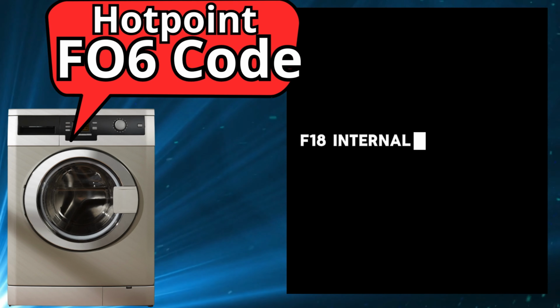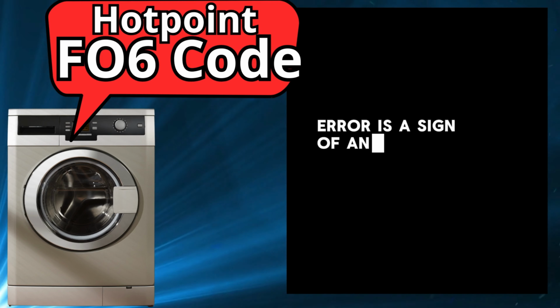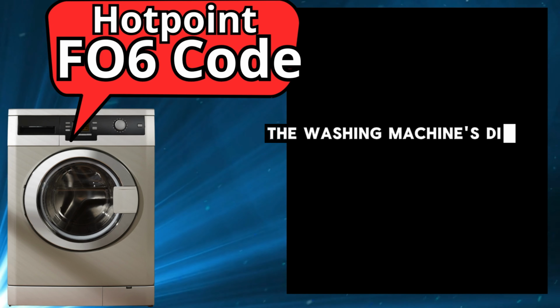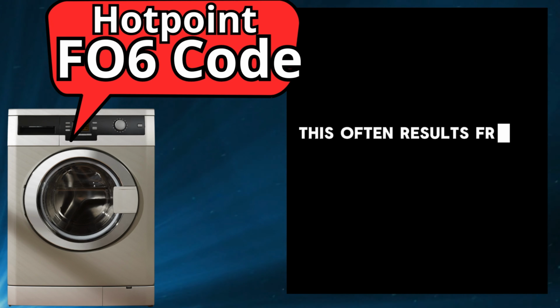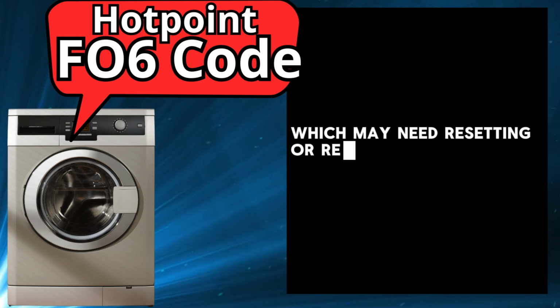F18, internal data error. An F18 error is a sign of an internal data processing fault. You may notice that the washing machine's display is unresponsive or that some or all functions do not work correctly. This often results from corrupted data in the electronic control board, which may need resetting or reprogramming.